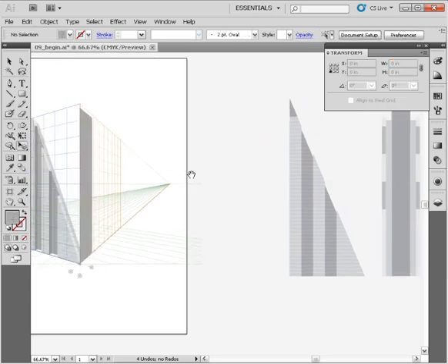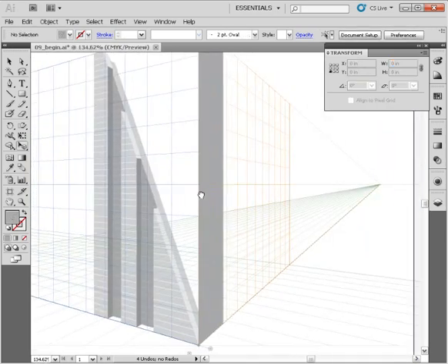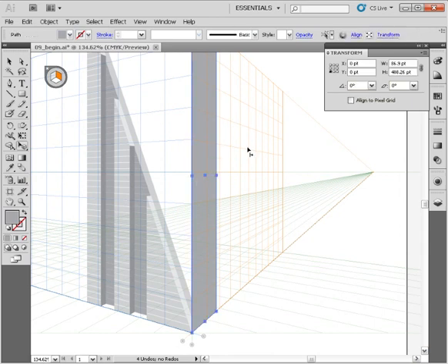This next part, you may or may not know about some of the number entry fields in Illustrator. Let's take that value and select this object here. I'm going to select, again, a reference point on the right side, so let's move it back to that bottom right corner. Now, we can actually input a mathematical calculation into this width field. Right now it's set as 86.9 points. You can see that we had our unit of measure converted to points. Let's input a minus sign and paste in the value we just copied, so we're telling it to subtract this much from our current value.